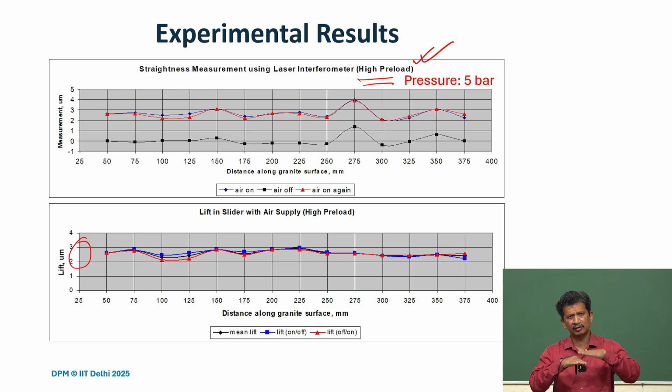So the flatness requirement, the surface quality of the granite block requirement is very high. It has to be within microns, and not just within microns, but maybe of the order of 0.2 micron. Can you achieve that? So that is a challenge. If we want to do business, want to develop systems made in India, we also have to check if we are getting granite blocks from Rajasthan or whoever is the supplier in India, how to get that? What kind of requirement is there?